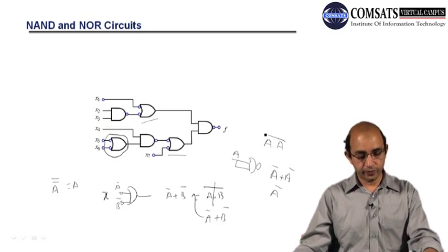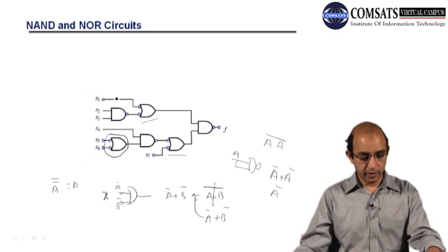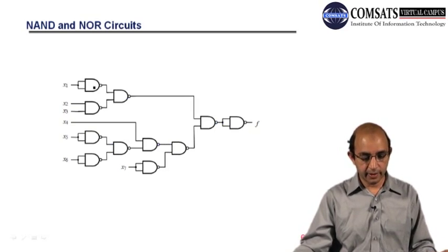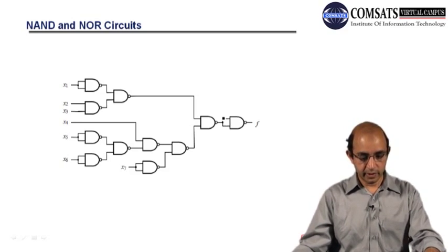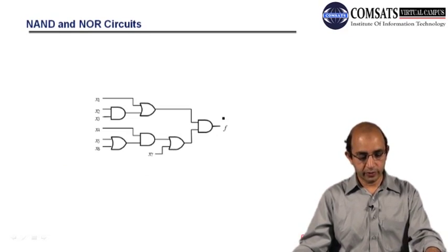Then you can see that this is the complement, right? So here we can introduce, so this is the NAND, this is also NAND. So we have all NAND implementation, right? Then what about the NOR, right? So we have to introduce the bubbles first, right?